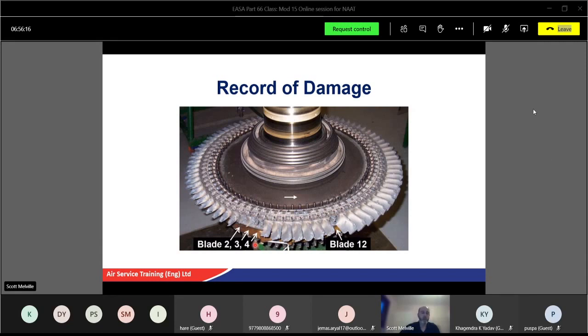We'd say maybe 4 blades found damaged, 2 times on leading edge, 1 on trailing edge, found to be within limits. So if you do find damage and it's within limits, you write that in the job card. 1 times blade found to have erosion of leading edge, found to be within limits. 1 times blade found to have tear of trailing edge, found to be out of limits, turbine to be rejected or engine to be replaced. Okay, so that leaves an open entry in the job card for the work to continue. Make sure it's an open entry so that the job card doesn't get finished off. Again, you'll learn more about that as you actually do it.